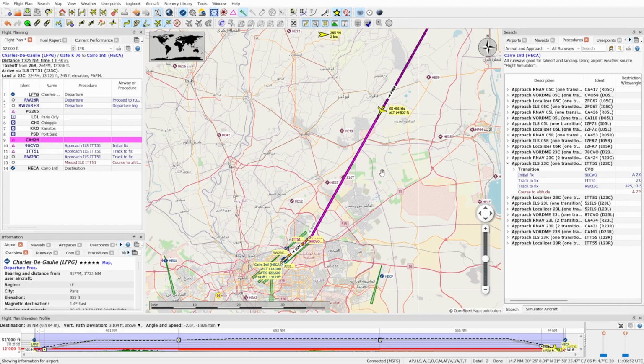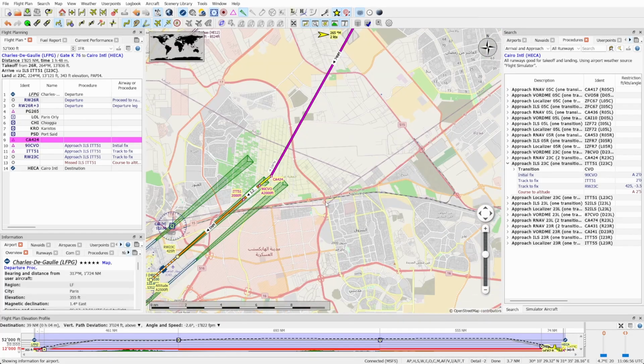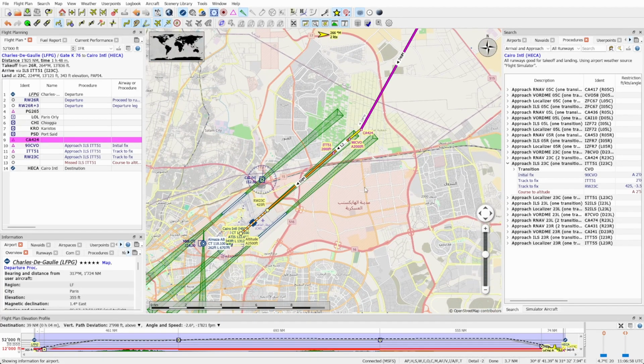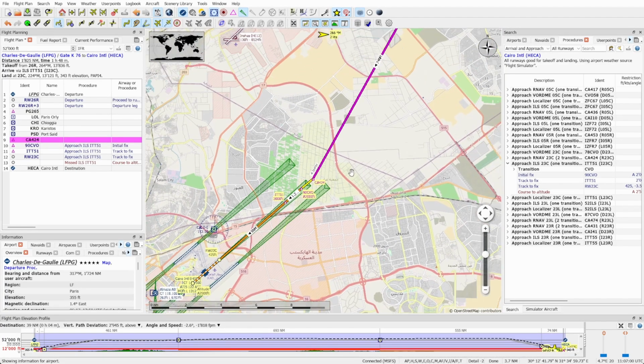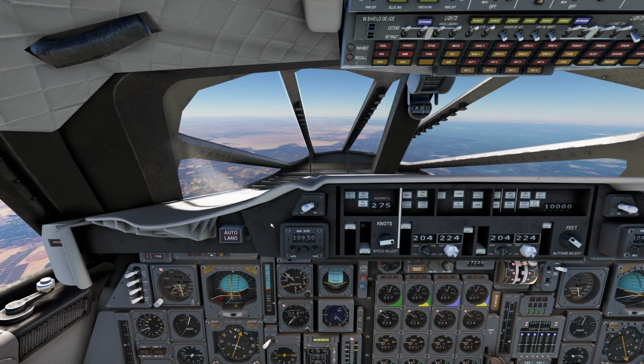We are approaching the entry point, 2,000 feet, where we're going to turn to the ILS heading 224. As soon as the beam comes in, in Flight Simulator, the autopilot, we go to glide. We could also do just a VOR lock or fly the whole thing manually, of course.